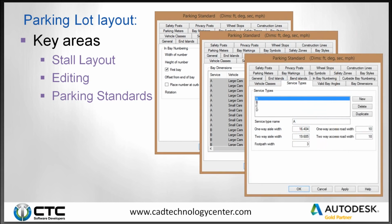And then the last thing, with the services, is there's 4 by default, and that's where you just set those. If it's a one-way, the width is 16.4. If it's two-way, it's 19.6. Well, you have the capability here of creating a new service type, and I created one for fun in another drawing that was parallel. I put in a service type of P because I wanted to do parallel parking. Because it's parallel parking, I had it as one-way traffic, and I set it up as 14 feet because all I needed was that extra lane right next to it.